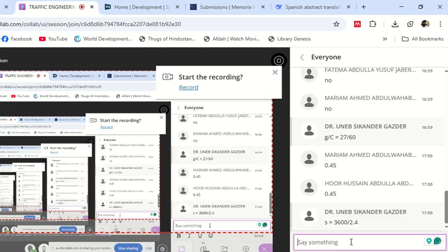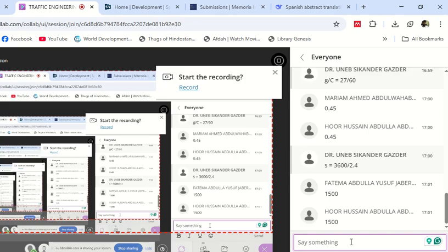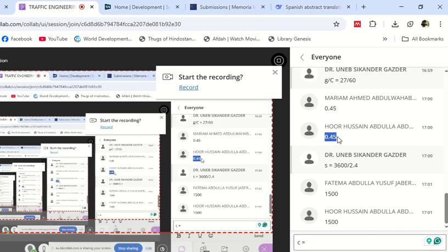So how much is this? Okay, so this is without any lost time, right? This is when the whole cycle is effective green, but I know the whole cycle is not effective green. I know only 0.45 of the cycle is effective green, G by C is 0.45.